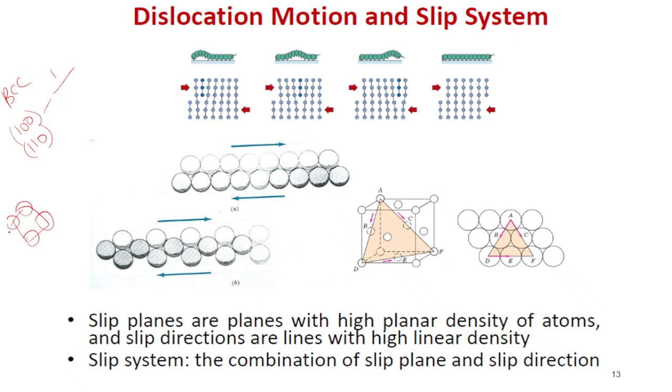The lattice parameter a is 4 by root 3 r, which we would have seen in our problem for getting the lattice parameter from the radius of BCC. So here it's a square, area a square. Roughly, if we take iron at 912 degrees, it will be BCC. The radius is around 0.1732, I guess.